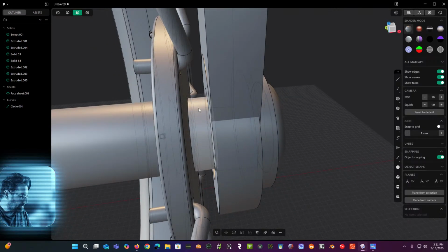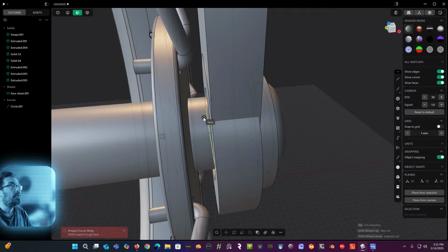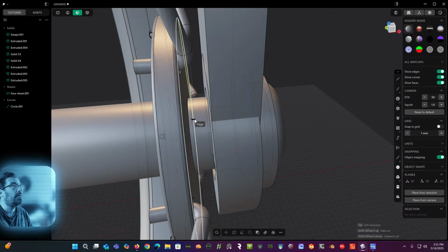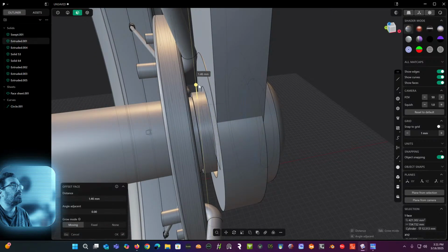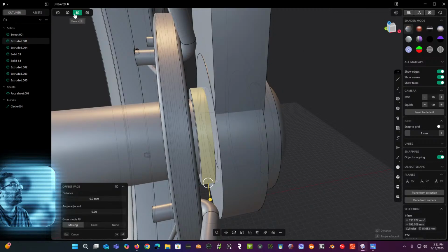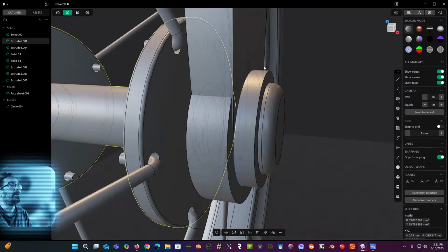And that's going to be really easy because all I need to do is insert an isoparam, Control R here, but we're going to tab and select it the other way. And then I'm just going to say U right there, grab the face, pull this slightly out. And now we've got that little sleeve. And I'm going to come in here now and just knock down some of those.